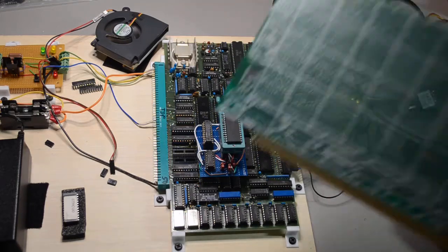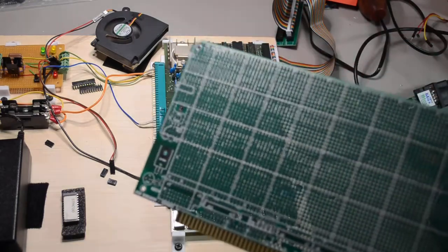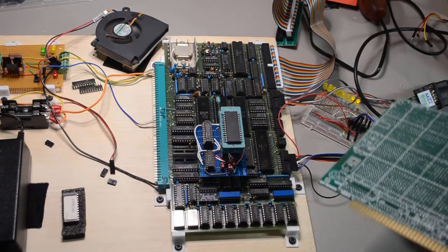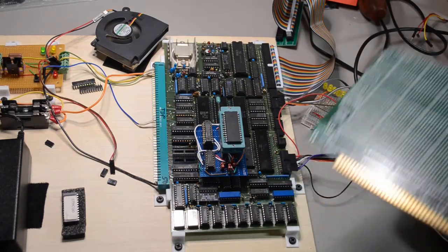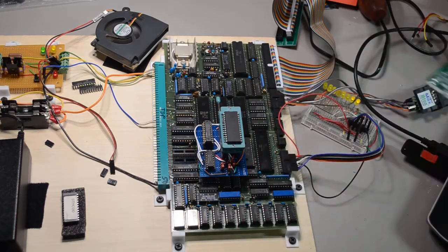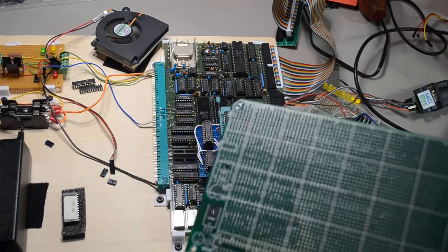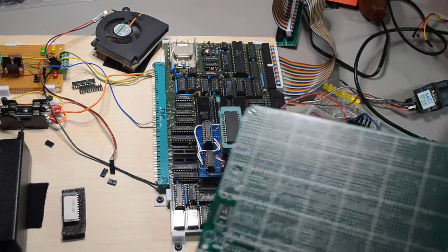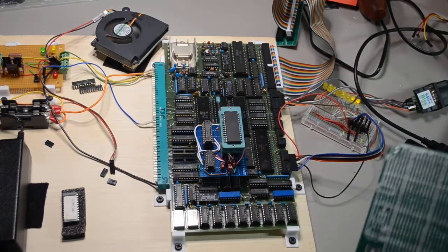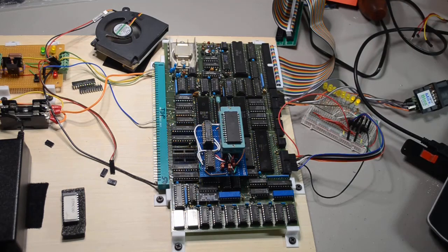I could even install the missing 16K of RAM on this board, or one of these boards, and get the system back up to 48K with BASIC installed again. It's the long way around to do it, but I could do it. If I'm going to build up a system, that's the way. I could wind up with an instant-on system with BASIC, 48K of RAM, plus I could put the CF card hardware on here and have the ability to boot into CP/M off of that and have a full-fledged CP/M system like this was actually designed to be. So that's a possibility down the road too.